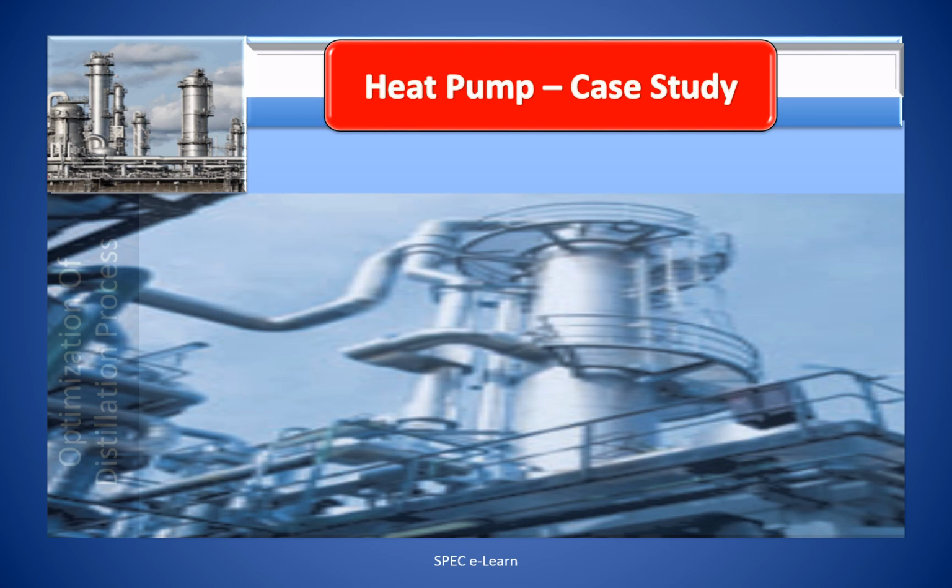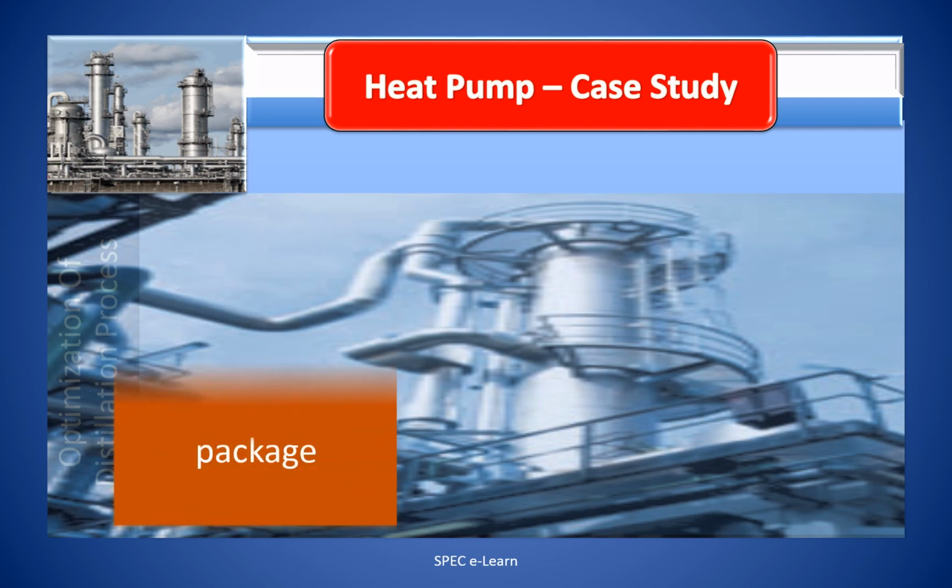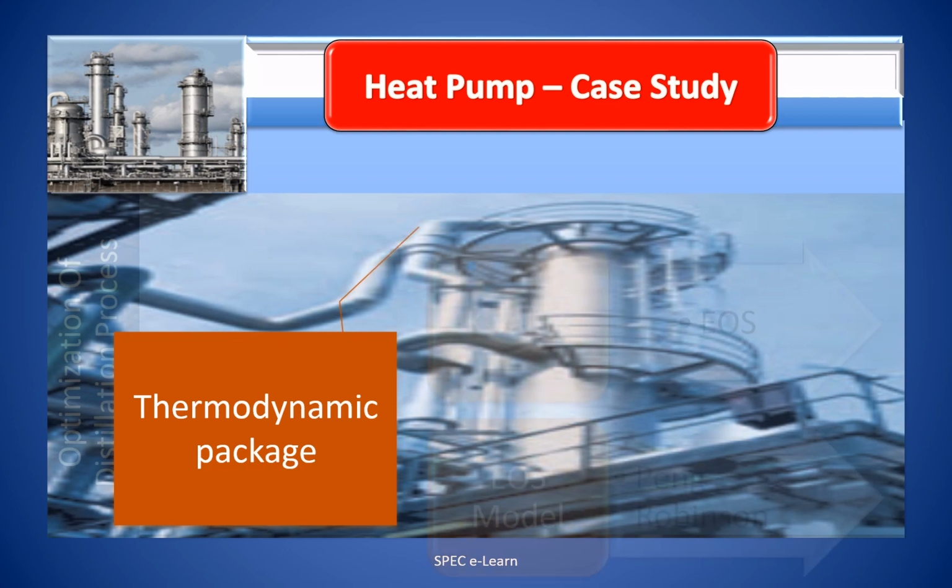Now select the thermodynamic package for the simulation. K value, equation of state model, Peng-Robinson.